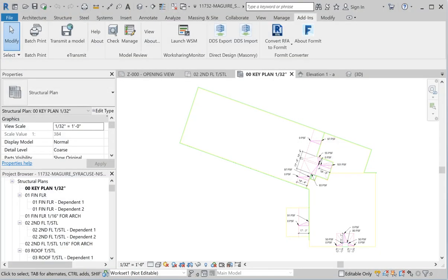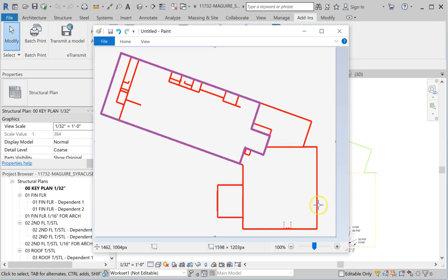So let's have a look at the Revit model that we're going to use here for this example. This is a plan view. You can see these light greenish walls are all the walls in the model, and specifically this darker perimeter here represents the structural masonry walls. We've got another illustration of this just to make sure we can really have it in mind as we work through this. So this purple perimeter here, these walls are masonry. These are the ones that we want to bring in with our import process.